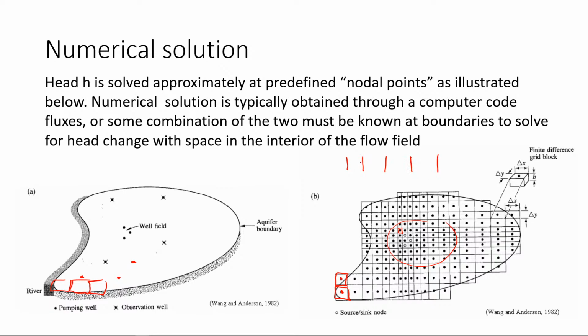That time step could be 1 day, or 1 month, or 6 months, or 10 minutes, depending on the objective of your study. That will give you the head value for that time period, for example for the whole day. If you wanted every 12 hours, then you discretize it every 12 hours, and that will give you the head value for those 12 hours.